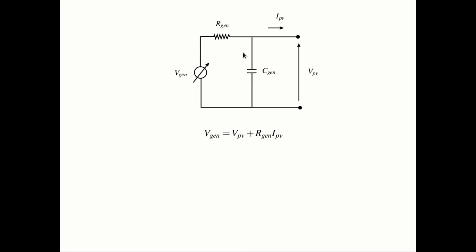Now you might ask, why this capacitor? The reason is we are measuring the voltage across the PV panel. Measuring the voltage across a PV panel, just if there is a resistance in another part of the circuit, may result in an unstable value. The best way to get a stable value is to place a small capacitor, as this capacitor will stabilize the voltage and give you a stable value always. Without the capacitor, you might end up with some amount of jitter. Try it out and check it for yourself.